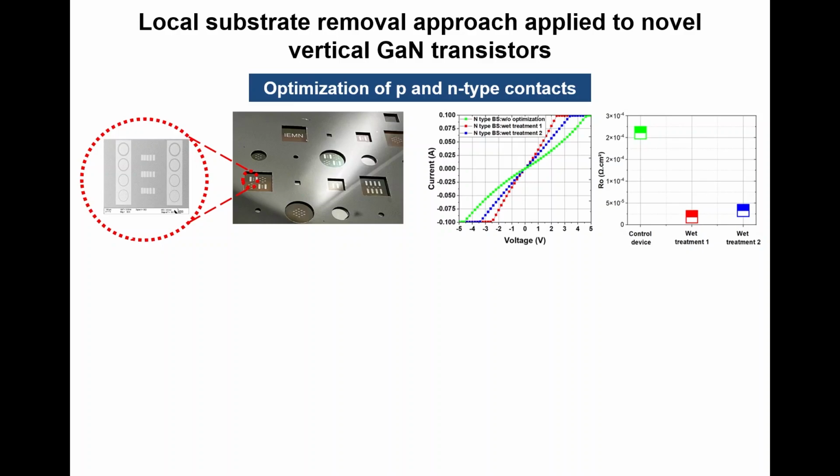We've been developing, for example, large area substrate removal. In this case, you also need to etch all the buffer layers, not just the substrate. So it's about 2 microns plus that you need to etch further. So we implemented some TLMs by laser writing here, and that allowed us to significantly optimize the contact resistance on the backside. This was not trivial.